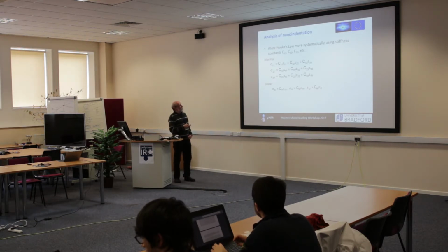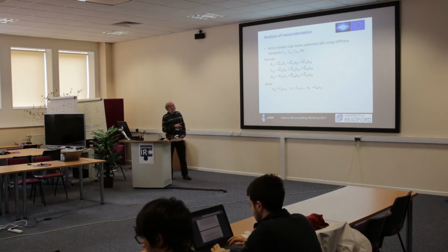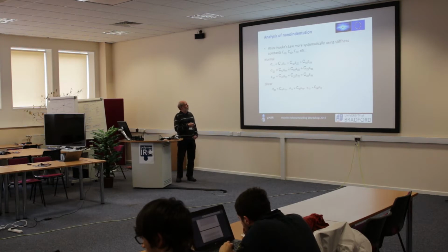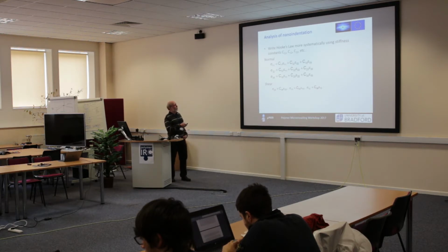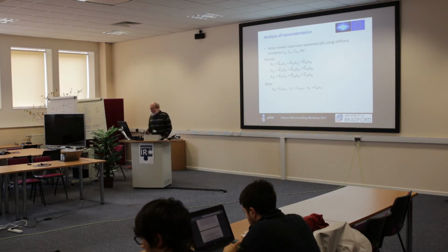So this is, basically, it's a good idea to dump Poisson's ratios because they're confusing, because nu12, for instance, doesn't equal nu21. And you always forget which is which. So C12 does equal C21. So we've got the symmetric type matrix behavior there. So, okay, suppose we've got these elastic constants.